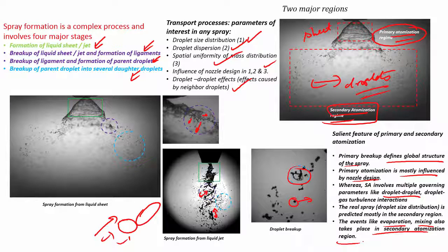Normally the atomization process is very fast, very quick compared to the evaporation process. So, you can take that evaporation only starts to happen after the droplets have substantially reduced in size. There is evaporation that continues to happen always, but if you talk about the dominance of the scales, atomization happens at a much earlier time.